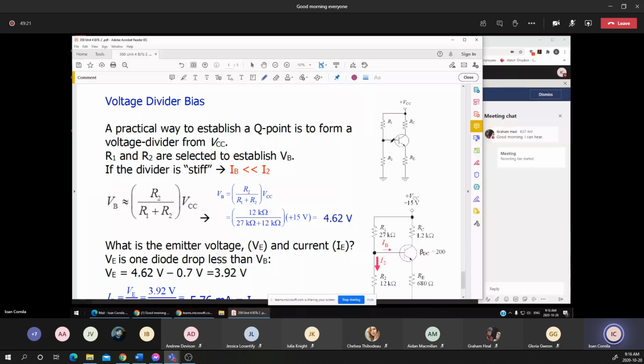Now is the time to explain and see the approach. I mentioned that for the first circuit, or the first calculations, make the assumption that we have no idea about the transistor. Now we know that the base current is very small, in terms of a few tenths of microamps up to probably 1 or 2 milliamps, no more than that, in order to have R1 and R2 connected in series, which will act as a voltage divider.